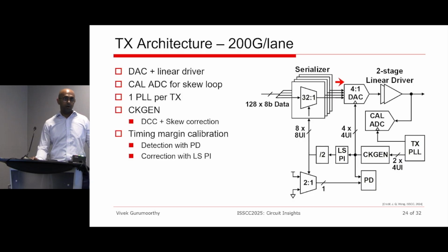We established that the clock rate was 14 there, right? Now we are trying to quadruple the data rate, but can we really quadruple the clock rate? So 14 times 4 will be 56 gigahertz. Trying to transmit 56 gigahertz inside a CMOS circuit is going to be next to impossible, right? So what do we do then? We keep the clock rate low, but we make the data more parallel.